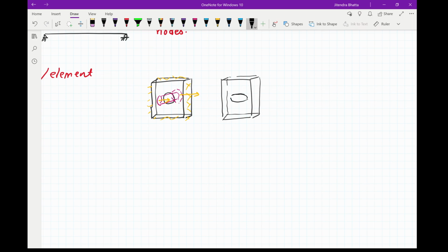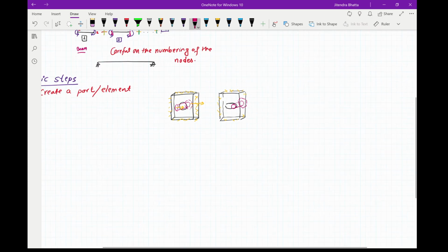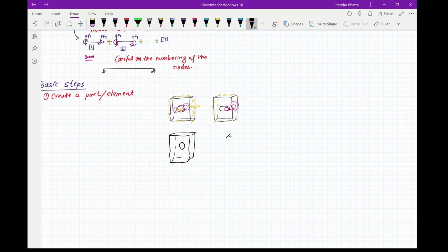The hole may get stretched like this and your bolt will reach here, because generally the bolts are stronger than the steel. They are generally of grade 800 MPa, whereas the plate may be of 250 or 550 MPa. Now to do this, you have to form 2 parts. You have to form a plate and you have to make a bolt. So this involves making 2 parts. This is part 1, that's part 2. This is actually a procedure in FEM